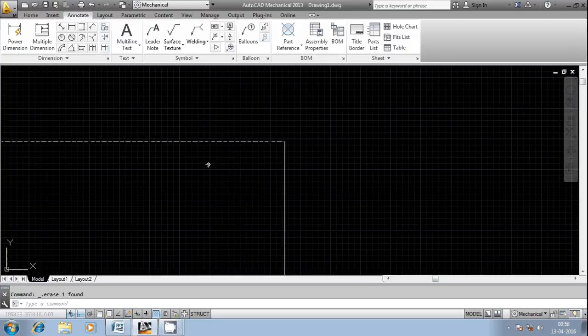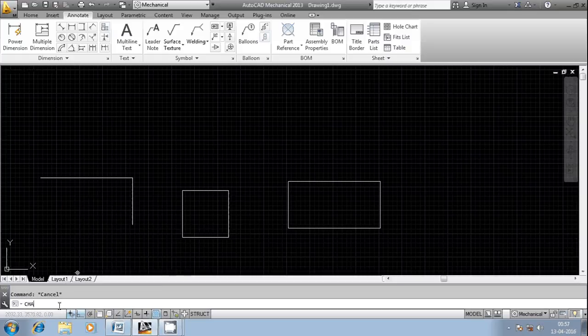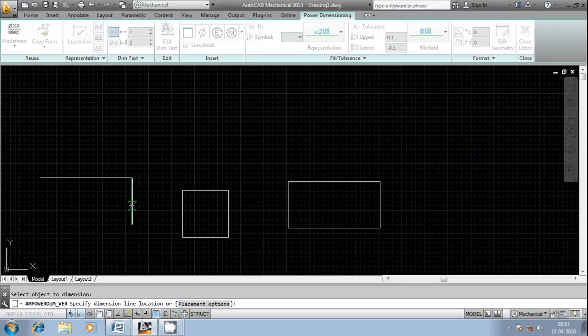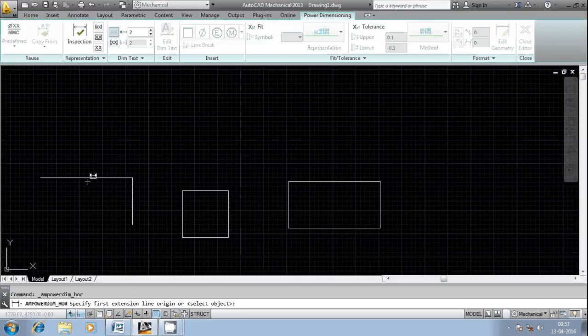I'm going to delete this and then perform the other operations as per my requirement. So let us invoke the chamfer command once again. Go to chamfer. Either you can go to setup straight away, or you can provide the angle value or the distance value. So I'm going to enter the distance. One thing you have to remember here is you should enter the distance value. Here it is 500, and then the other entity is something bigger than that.